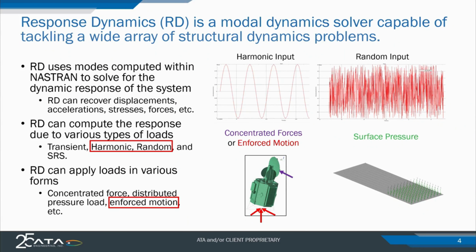Response dynamics can also apply these loads in a number of different types of loading conditions. So everything from a concentrated load to distributed pressures, enforced displacements, accelerations, etc. Today we'll be focused mainly on the enforced motion, since that is what this new solver type is capable of.